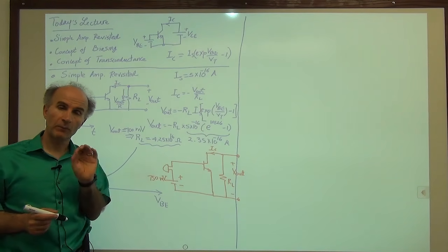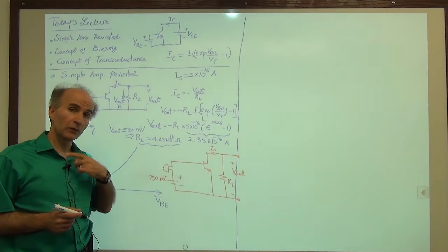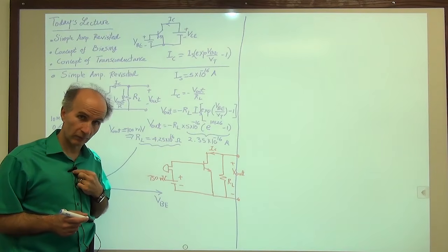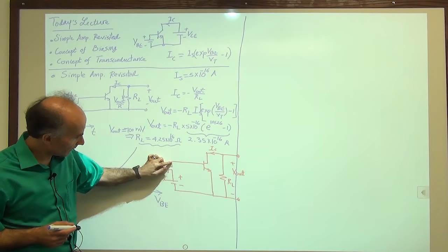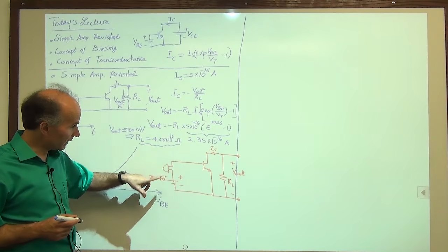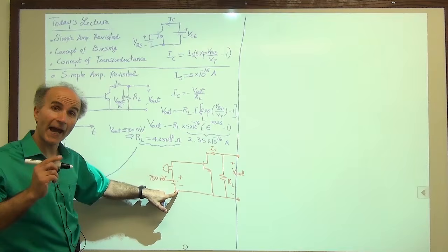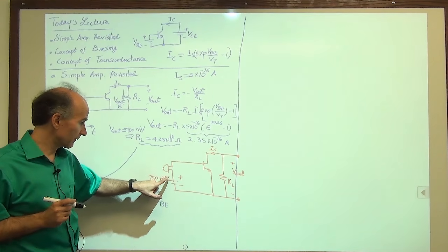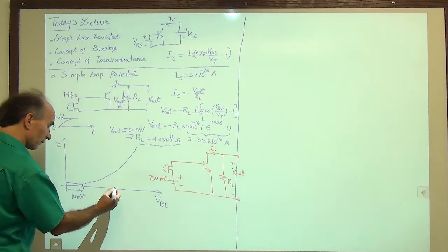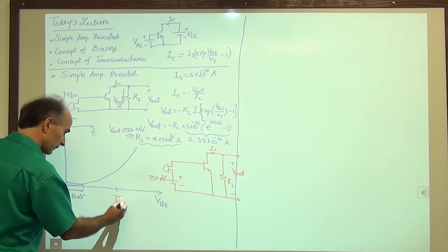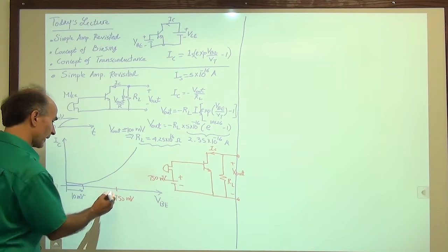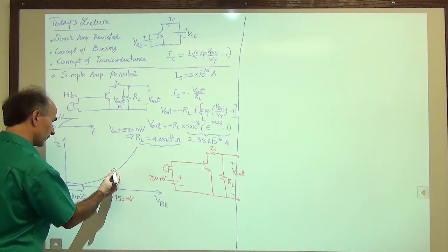Okay, so for the moment, let's say I am not speaking to the microphone. So the microphone produces 0 volts. 0 volts means from here to here 0 volts. It's just like a short circuit, right? No voltage. So that means that the base emitter voltage in the absence of a signal is 750 millivolts. So let's go find that on this plot. 750 millivolts is somewhere around here. Of course, this is not to scale. And at 750 millivolts, we have a certain current.